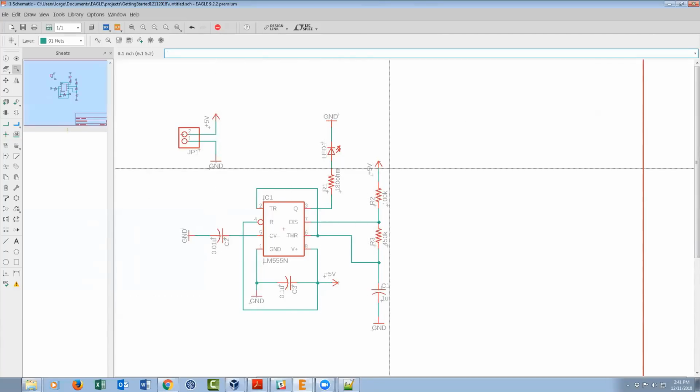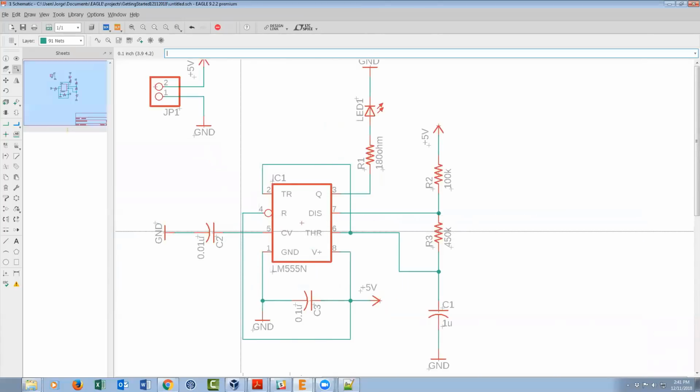And what that allows you to do is to have a very readable schematic. It makes it easier to read because you don't have a lot of lines overlapping each other. So like in this design, you only have two main nets that overlap, which is this one, and really there's no way around it, and this one here. Okay? And you can tell that they're not connecting even though they intersect because there's no dot. Okay, if there's no dot, they don't connect. That's how you can tell.